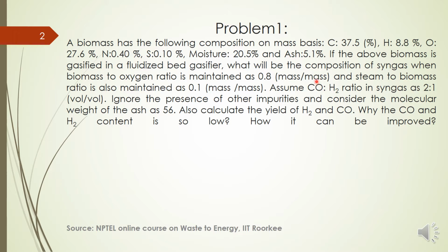And we have to balance on both sides all the elements, carbon, hydrogen, etc. And we will get a number of equations and solve those equations incorporating this clue also. So like that we can find out the syngas composition. So that is the step.